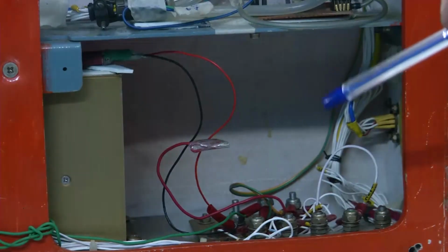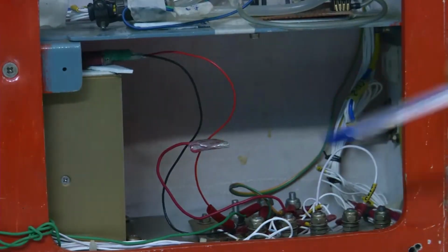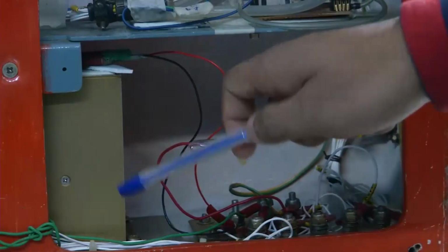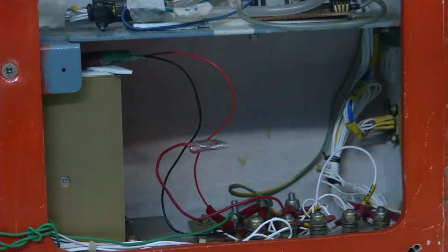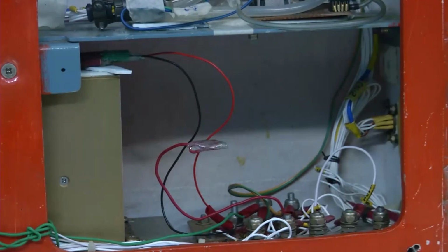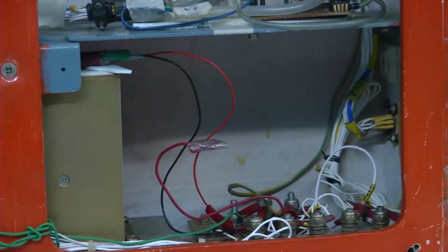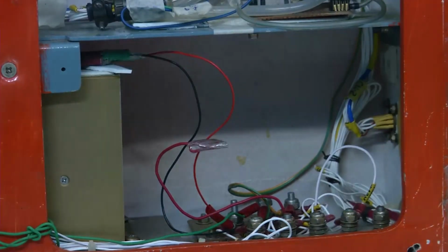Now as far as accuracy is concerned, your IMU can measure acceleration up to plus or minus 4G, with an accuracy of less than 0.5 G. As far as your roll and pitch angles are concerned, it can go from minus 180 to 180 degrees in the case of roll, whereas for pitch it can go from minus 90 to 90, with an accuracy of less than 0.1 degrees.